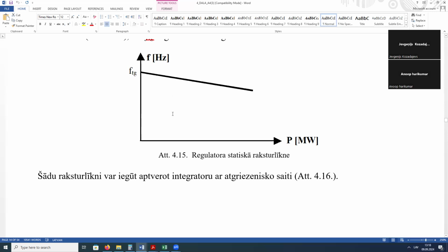Okay, this is true for one generator, and for every generator regulator that participates in power balancing in this regulation. Because, for example, we could have a lot of small generators that are just connected in parallel to the power network without any generation regulation. Why? Because it just goes in parallel. If frequency in the system rises, it starts to rotate faster, without any regulation, just in parallel. Such types of generators don't participate in this regulation.